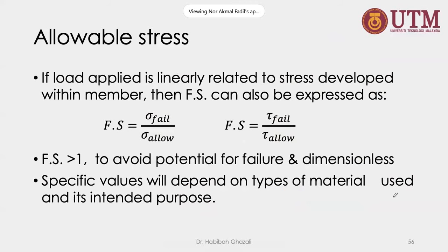If the load applied is linearly related to the stress developed within the member, then it can be expressed as the stress divided by the allowable stress. Factor of safety must be larger than 1 to avoid potential of failure, and it is dimensionless. It doesn't have dimension. The specific value will depend on the type of materials used and its intended purpose.